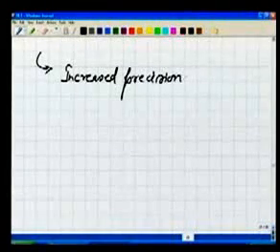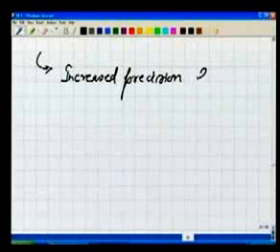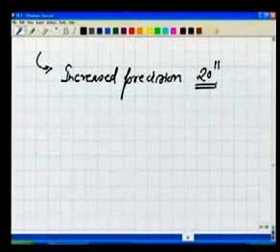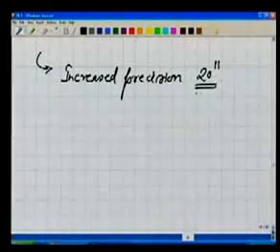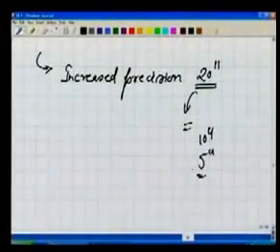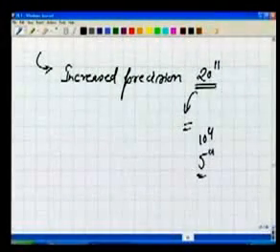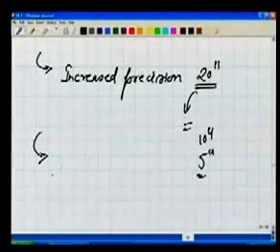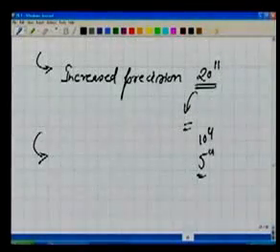What is the meaning of that? The meaning is, if our theodolite is a 20-second theodolite, the least count is 20 seconds, we improve the precision. We try to increase this further down, maybe 10 seconds, 5 seconds, by this particular method. Number two, we also eliminate some errors which are in the theodolite. We'll talk about these errors in detail later on.